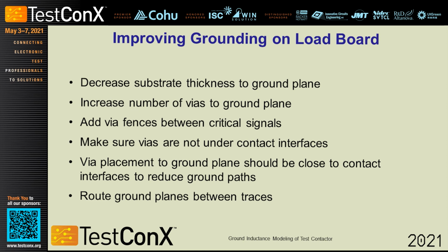When you move grounds closer to the RF signals, you tend to lower the impedance. If you actually have a signal and ground far away, the impedance is fairly high, but as you move that ground closer to the RF signal, it tends to decrease the impedance a little bit. Obviously, if they touch, you have 0 ohms because the signal is basically shorted to ground.